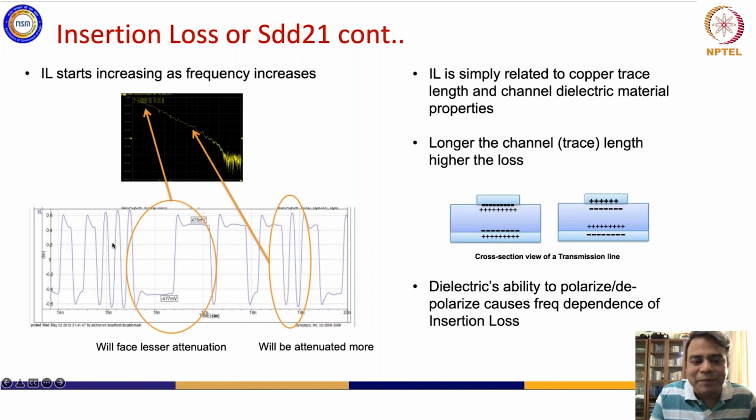When you look at that bit period or that bit diagram, multiple zeros followed by multiple ones is a lower frequency, right? Because the time period is high. When the bit pattern is a continuous sequence of zeros and ones, the frequency is higher. So you're actually transmitting a wide range of frequencies. It's a wide band. And obviously, when you transmit the lower frequencies, the attenuation of the media to these frequencies corresponds to the left side of the spectrum. When you go to higher frequencies, you have more attenuation. That is a standard property of copper conductors.